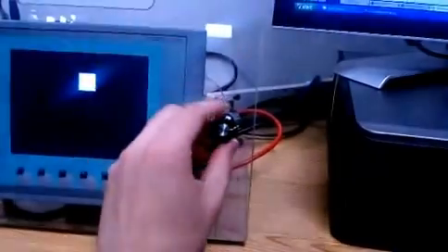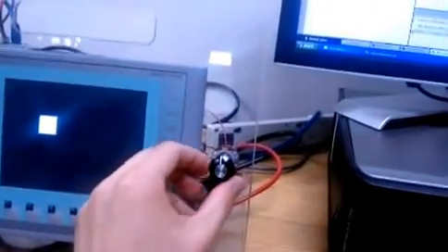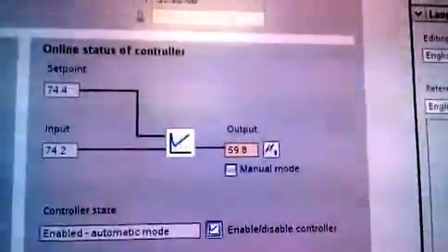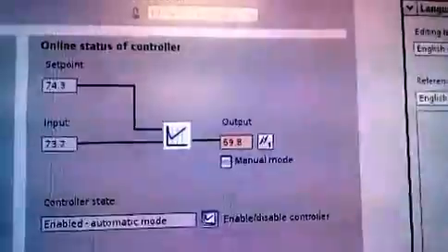You turn the set point to somewhere where normally you want it full, but you're going to set it in the middle. And then you hit start. And you see there the PLC is going to try to calibrate itself. It's going to set the input and output.